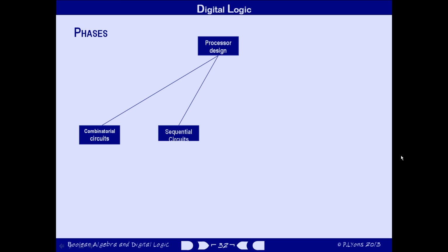The next most complex type of circuit is called the sequential circuit. Sequential circuits may, and usually do, have external inputs, like the combinatorial circuits, but they also have a feedback path, so that one or more of their outputs is sent around again and used as an input. Sequential devices are thus a function of current inputs and previous outputs. They allow us to design useful things like memory and state machines, which are sort of like simple programs implemented in hardware instead of software.